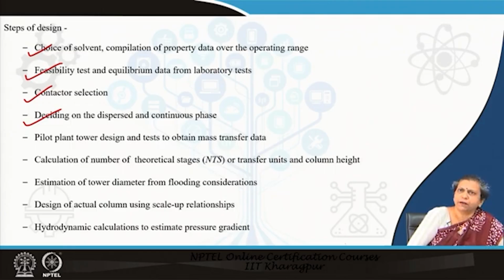I had also mentioned that although for vapor liquid contacting in distillation we often prefer the bubble cap tray, in this case, due to low throughput and low efficiency of the bubble cap tray, we do not go for the bubble cap tray.